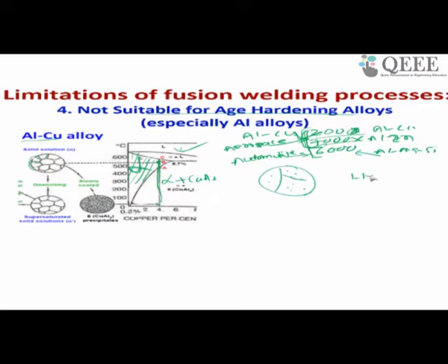So what do they do? They heat to obtain a single phase, and that is called solution treatment. This ST means solution treatment. It means they heat to obtain single phase, then they quickly quench, so then they do quenching.